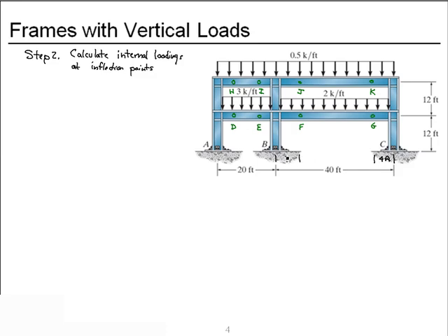These two are 4 feet in from the center of the column, and that means that in between the two there's 32 feet left. E and I exist 2 feet from the center of the column. D and H exist 2 feet from the center of the column, and that leaves a 16-foot span in between the inflection points.